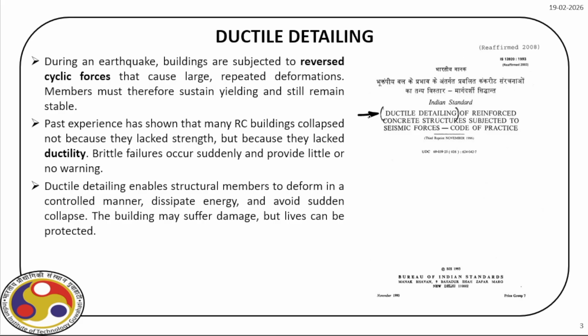Now, if you recall, we discussed the design of a singly reinforced beam section. So if you have, say, this is the section, then our first task was to find out the neutral axis, right? And then the concrete above the neutral axis, which is in compression, we consider, but the concrete below the neutral axis we ignore, we only consider the steel, right?